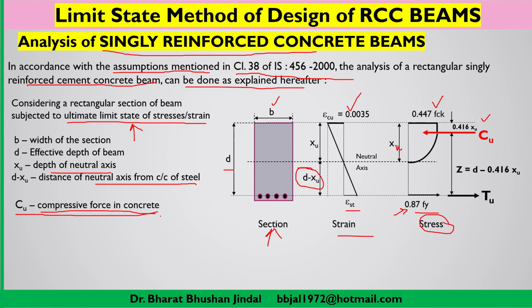Similarly, Tu is the tensile force in the steel at the ultimate limit state. That's why we have taken the abbreviation Tu, where T is for tension and u is for the ultimate state. So Cu is the compressive force in the concrete at the ultimate limit state, and Tu is the tensile force in the steel.